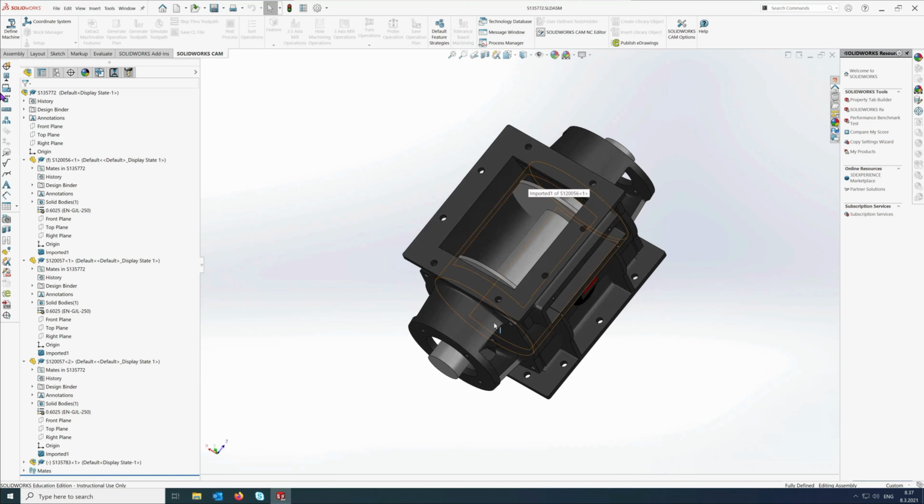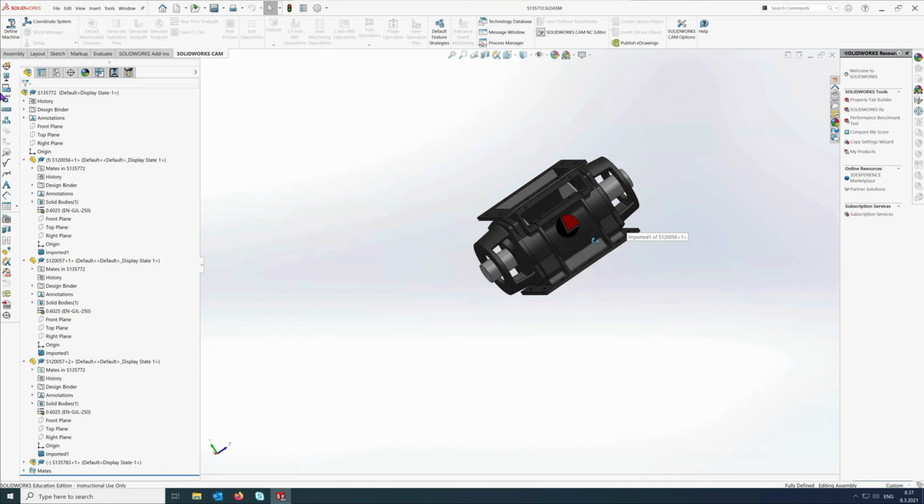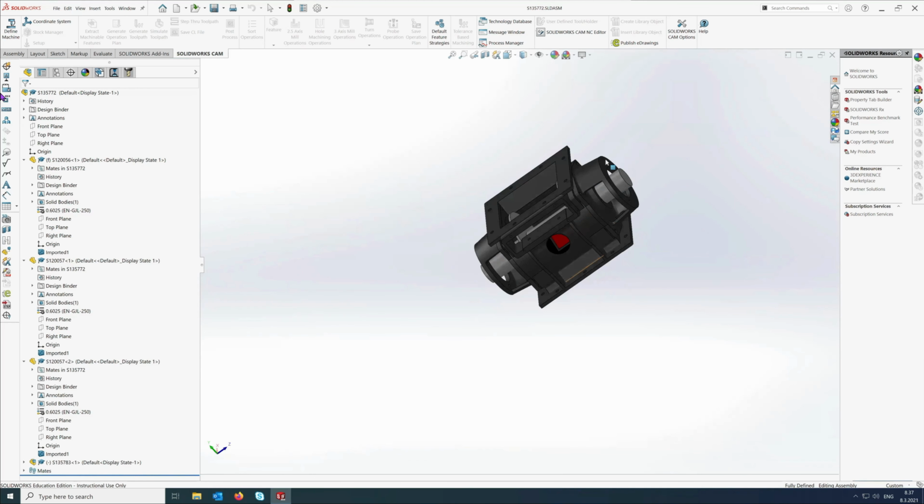But when you later attach a bearing here, and you attach the sealing unit here, then you know what the correct dimensions are. And also on the other side, later you are going to select a gear motor here, and based on those dimensions that come from the standard parts, you are able to modify this rotor to be correct. Okay, thank you.